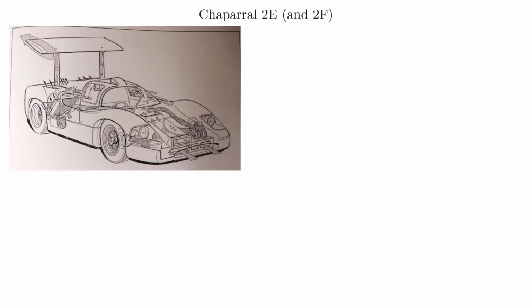So we can see from this schematic that they have the air being redirected at the front, and as you take it in the front and release it out the hood, that generates downforce as well. So what they could do was just close off that flap, so they could block it when they didn't want that air to generate the downforce at the front. And then you could release a flap that would let that air flow through when you needed more downforce at the front. And the way they controlled this was brilliant.